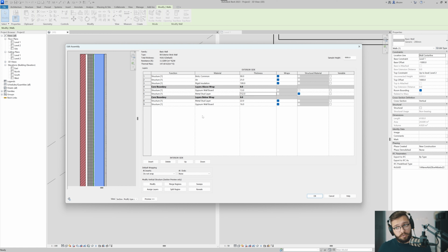Now, one thing I want you to pay attention to. This is the quick and dirty way of doing it. If you work in a company where you actually want to extract quantities, all right, instead of just having metal stud layer, you would have a specific material which is properly described. You would have something that says, let's say, a 22 millimeter resilient channel. Perfect. So you can actually take out the square footage of that so that you can make your calculations at the end. Instead of saying just gypsum wall board being super generic, I would say, no, this is 16 millimeter type whatever gypsum wall board, or let's say type X if it's fire rated. Here, instead of just gypsum wall board again for 30 millimeters, I would have a title which explains the whole thing. And I'll be able to say, this is 13 millimeters exterior grade gypsum wall board.